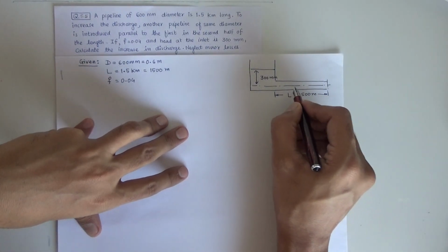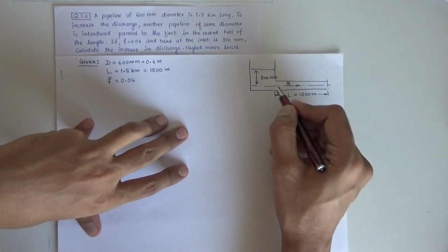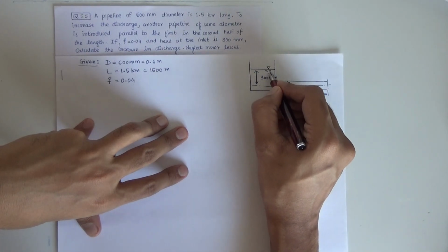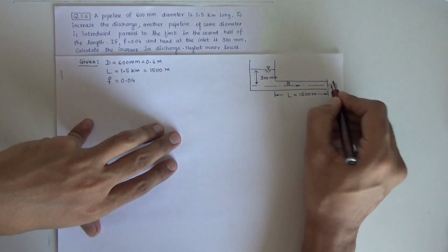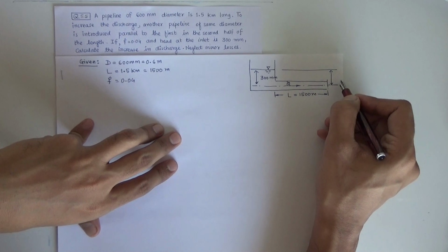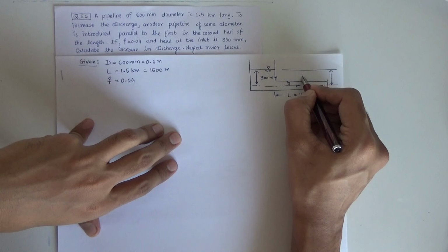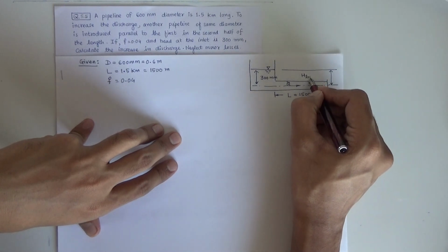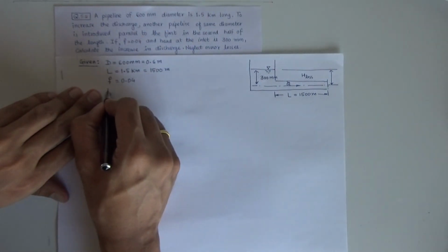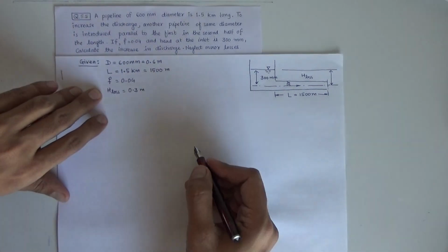Let us say Q dot is flowing through this, and how much is the loss now? As you can see, this is the head level at this side and the exit is open to atmosphere, so the loss will be the difference between the inlet and outlet. If the outlet had some reservoir, the level of that, let us say H1 minus H2, will be the H loss, but here H2 is 0, so H loss is completely 300 mm. So total H loss is 0.3 meter, that is 300 mm.